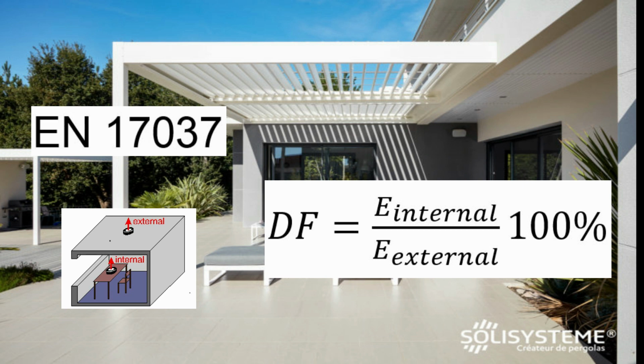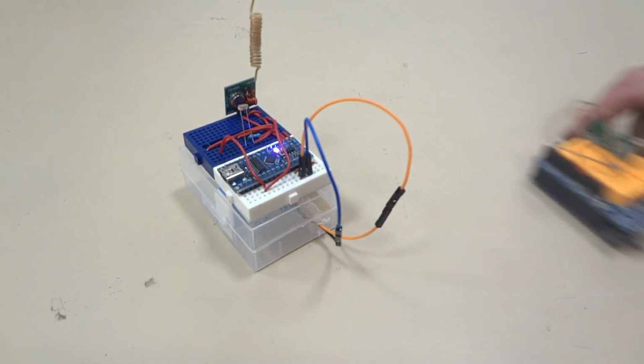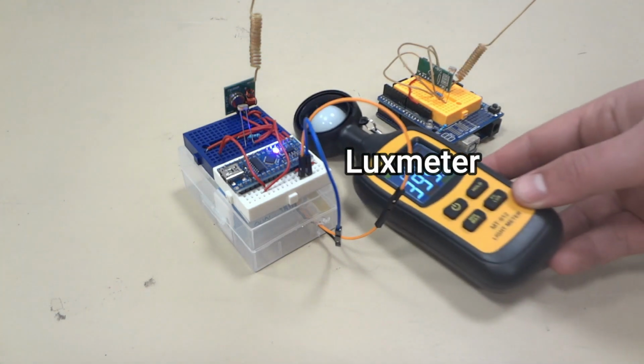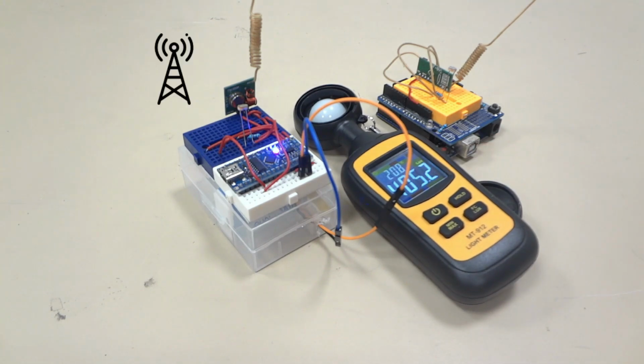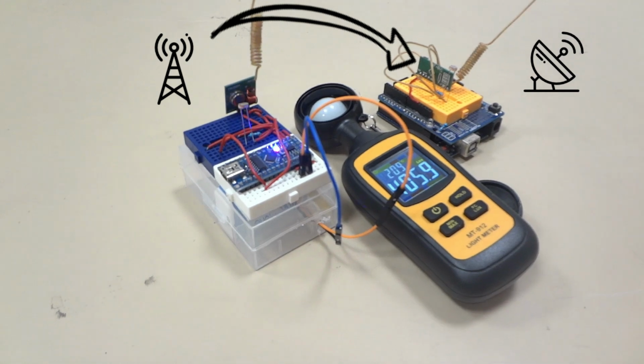The measurements have to be taken under some specific conditions, such as the position of photosensors and sky condition. To do the experiment, I made both internal and external photosensor circuits using the Arduino, and I brought a luxmeter to calibrate those photosensors. The internal sensor sends data to the external sensor through a radio communication. The external sensor combines both data and sends them to the computer through a serial communication. So I can place freely the internal sensor inside the pergola.